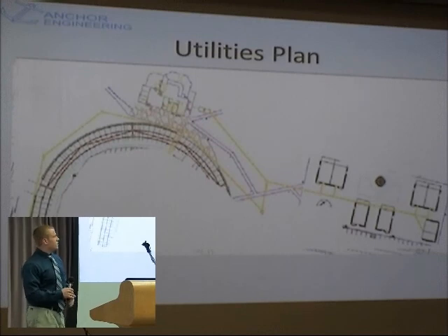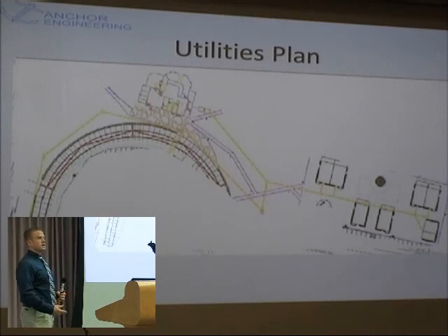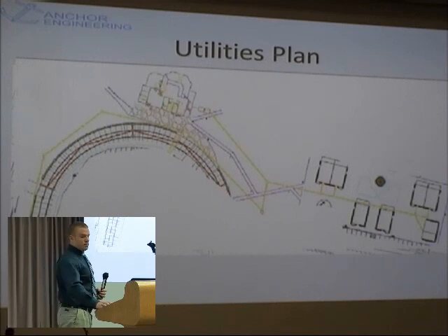To design the head, it was mostly due to pumping it up at such a high elevation, about 50 feet. That was pretty much controlling. I also had to account for friction and minor losses, which I used equivalent lengths to calculate.